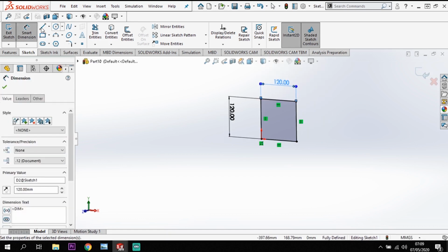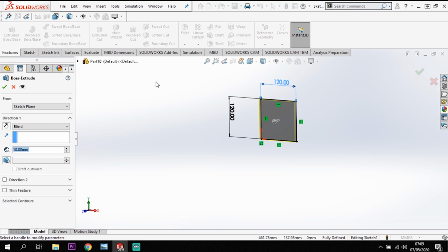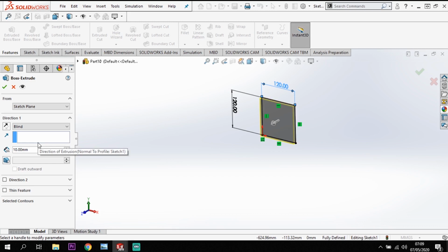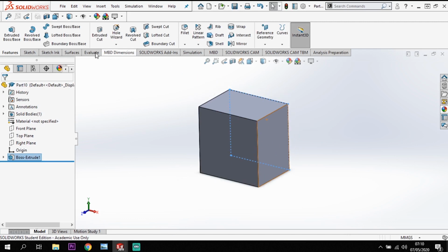Now these two components are going to fit together nicely. When we make them, they're going to be stuck together perfectly, so we need to make sure that the sizes are perfect. So I'm going to bring this forward by 90. And I'm going to tick there just to bring that shape out, so we've got that extrusion, like so.